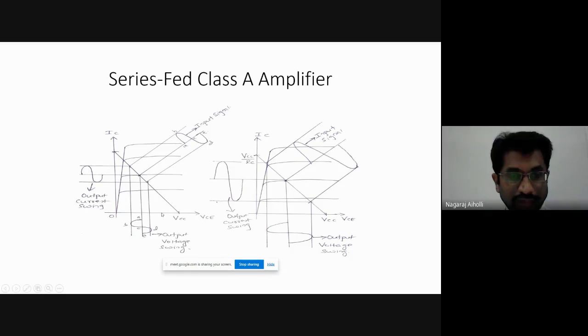Following? Then if I take the horizontal axis VCE, it is nothing but the output voltage, the collector to emitter voltage. Now how to draw this VCE? See here, I am marking certain points on this input signal: A, B, C, D, E. This is how I have to mark these points on the collector to emitter voltage to get the VCE. This line I am extending, the reference line. This is the top line, this will become the bottom line, and this is the bottom line, this will become the top line.